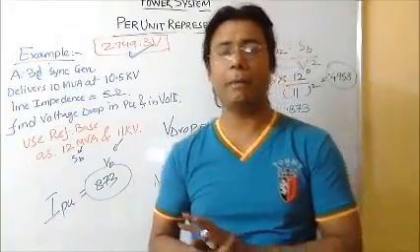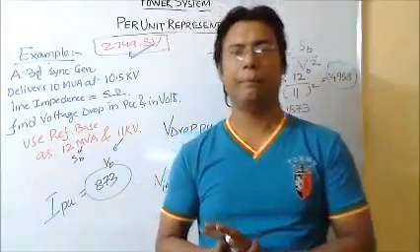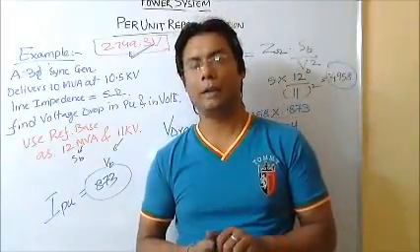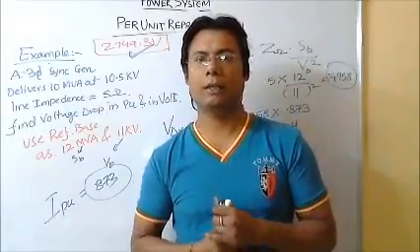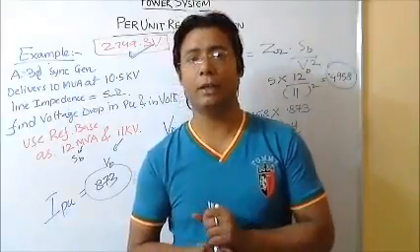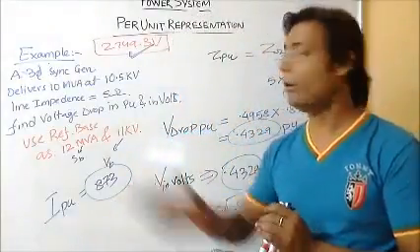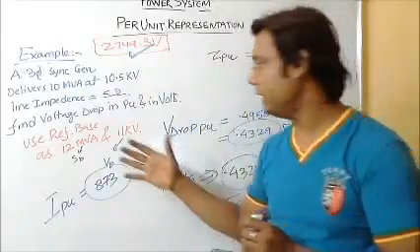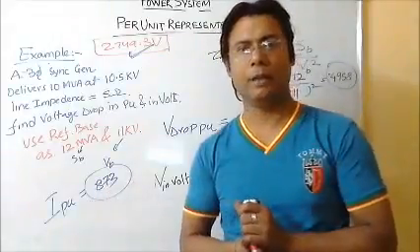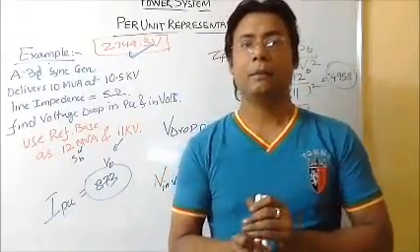There will not be any requirement of calculators or PCs to compute the voltage ratings, current ratings or KVA ratings. Since all the values are very small, we can compute them by manual method without computers and calculators. So rather than choosing everything in 10.5 kilovolts, 11 kilovolts, 12 MVA, we can have smaller values and compute them manually. So computation is very easy by per unit representation.